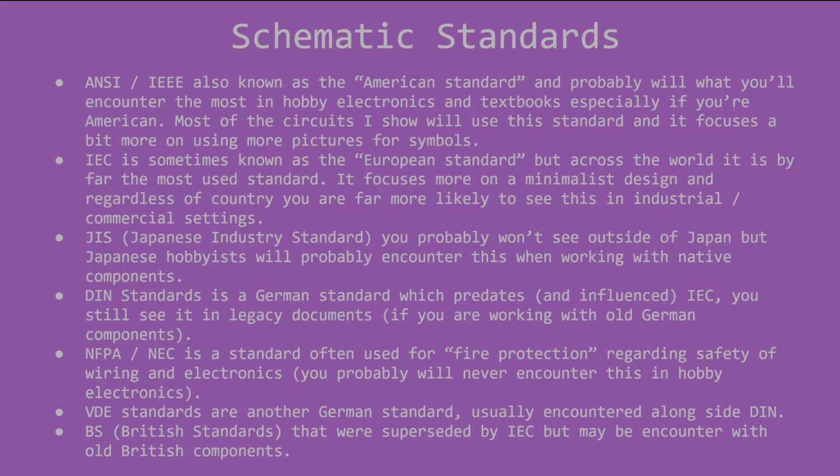Then there's JIS, which is Japanese Industry Standard. You probably won't see this much outside of Japanese electronics, and even then, there's a lot of Japanese electronic schematics that use IEEE or IEC, again, depending on the audience. If you deal with a lot of Japanese electronics, hobbyists, your student, whatever, you'll probably encounter it, but outside of that, I don't think so. There were some old German standards, DIN and VDE. They predated and influenced IEC. You might see these in some legacy German documents, but we're talking pre-unification. I think by the very late 80s, going into the 90s, they had already switched.